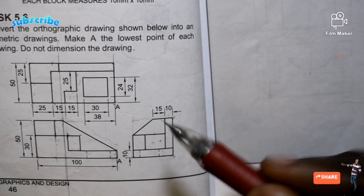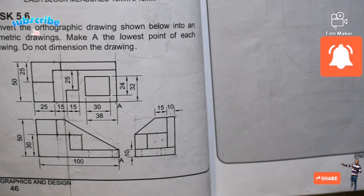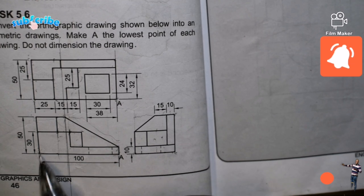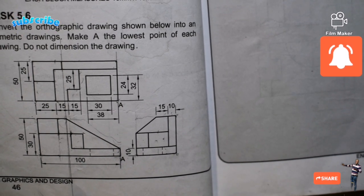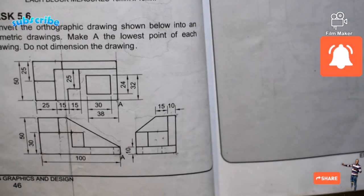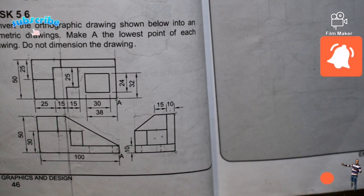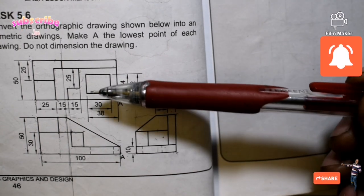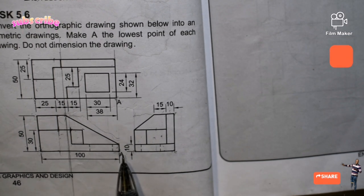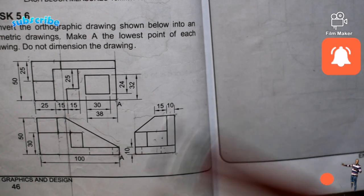Remember, the right view as well as the top view, they will share the same width. I mean, not length, but breadth or width. Remember, a length is there by your front view. So from there till there it's a length, from there till there is a width, from here till there it's a height, from there till there it's a height, from here till here it's a length. Which means the front view as well as the top view will always share the same length. Because if from here till there is 100, then from here till there would be the same 100, you understand.